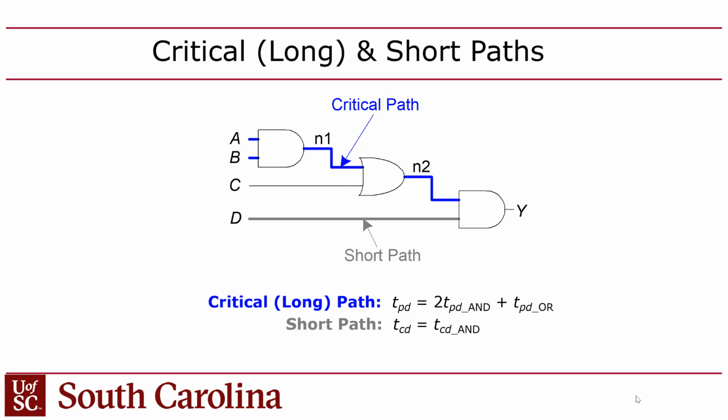Yes? But even for one circuit, is it a statistical thing, like under different conditions, even through the shortest path, you may have a contamination delay a little bit different because of temperature, noise, etc.? Yeah, that's true. Generally, you'll notice in the FPGA tools, I don't know if you've read the output from Quartus, but they have delay models for the FPGA at different temperatures. And when they report delays, they use the worst case temperature, which is usually 85 degrees Celsius. They consider that to be the highest temperature you'd operate the FPGA at.